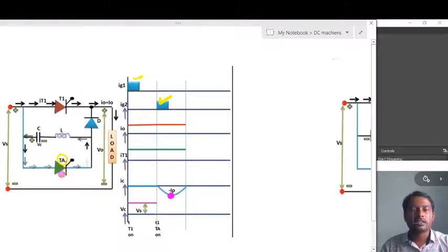If you turn on the auxiliary thyristor, the energy is transferred to the inductor through this auxiliary thyristor, and this acts as a tank circuit, and current flow through the inductor and capacitor will be sinusoidal in this way. While charging the inductor, polarities will be positive and negative, and if the total energy of the capacitor is transferred to the inductor, then after absorbing the total energy from the capacitor, the inductor will change its polarity, and it will discharge the energy to the capacitor in this direction, so that the capacitor will be charged here positive and negative.